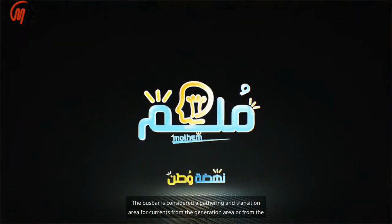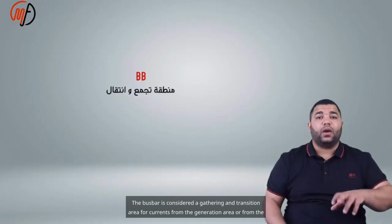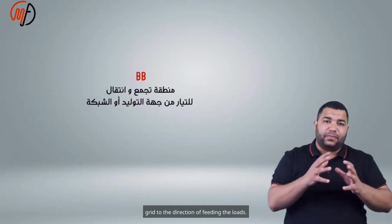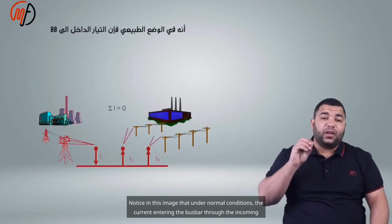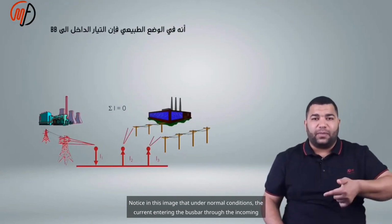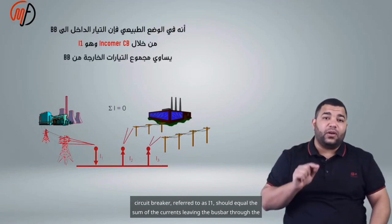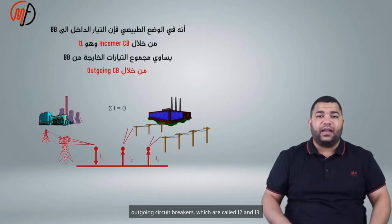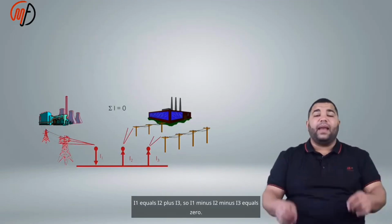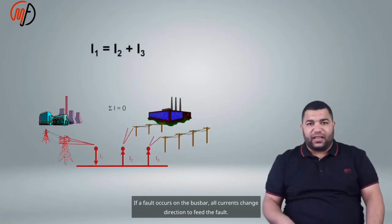The bus bar is considered a gathering and transition area for currents from the generation area or from the grid to the direction of feeding the loads. Notice in this image that under normal conditions, the current entering the bus bar through the incoming circuit breaker, referred to as I1, should equal the sum of the currents leaving the bus bar through the outgoing circuit breakers, which are called I2 and I3. I1 equals I2 plus I3, so I1 minus I2 minus I3 equals 0.